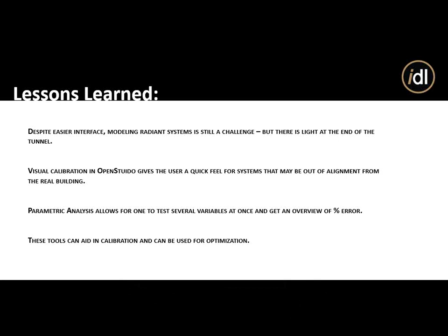I guess in our experience with OpenStudio, we found the controllers to be somewhat limited, and there's always some limitation. Even in the BCL library, a lot of times they don't give you a lot of information on what's in that script. I'm curious how you dealt with that workflow as far as writing Ruby scripts, or if you were going to EnergyPlus and back, or how you did that work.